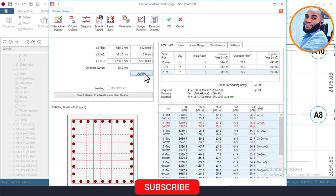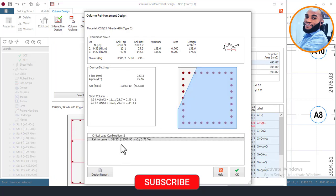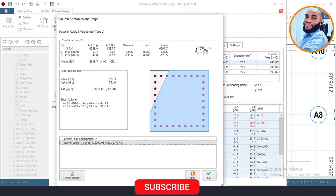So I'll come here right now and say okay, and then we set bars and design again. We'll have 28 number of bars, about 32. Okay, 32 is 32. That means the load coming on that column, yes, that's true, because this area of that column is where we have the swimming pool. Okay, that's fine, so that's why we're having that. So this is okay. 32 number of Y25 is okay.